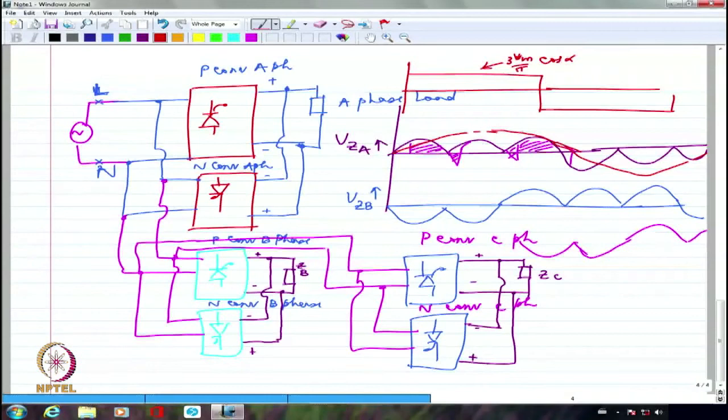And cycloconverters reduce the frequency. Most of the times, synchronous machines may be run at slow speeds, for some kind of cement mill where you are trying to grind limestone and so on. All those things work very slowly. It is inching. Most of the motor drives will be inching slowly. So in those cases, these can come in handy. From 50 hertz, you may come down to 10 hertz or 5 hertz. So in those cases, cycloconverters come in handy.